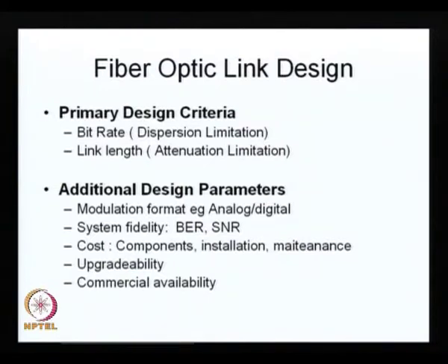For one communication link, you require only one fiber, but since the installation cost is substantial, when the fiber is laid, normally a multi core fiber is laid, keeping in view that at some later date there will be more need for bandwidth, and then the multiple fibers can be useful in meeting that requirement. So, installation cost is one of the major components of the optical communication link.